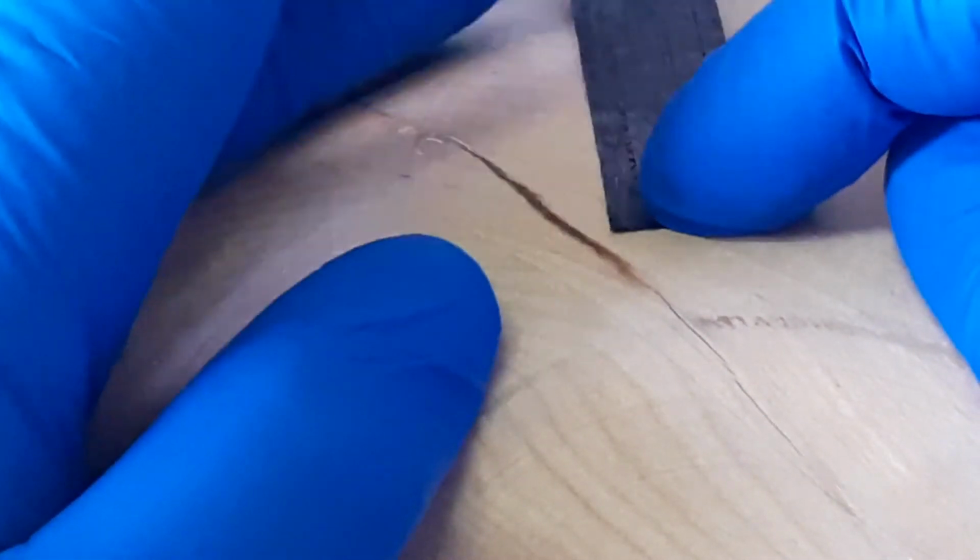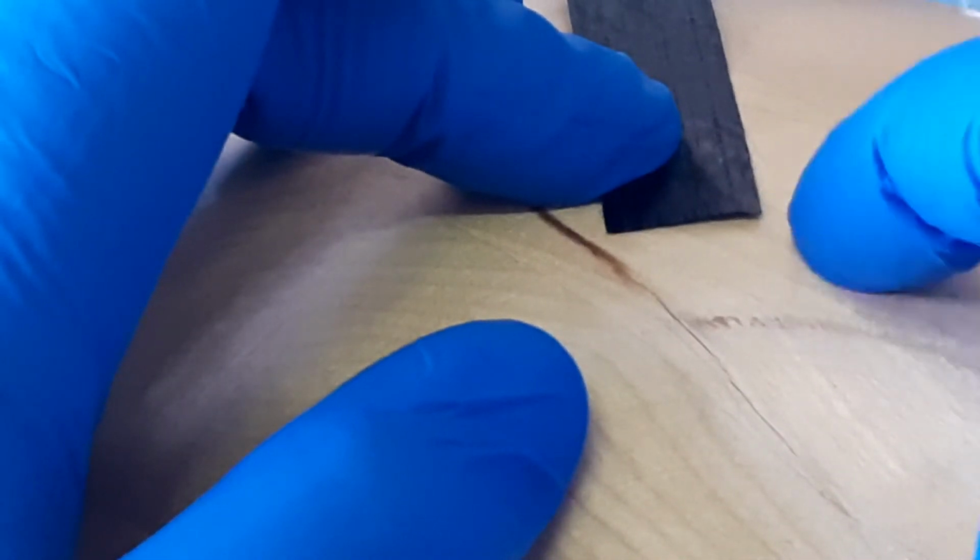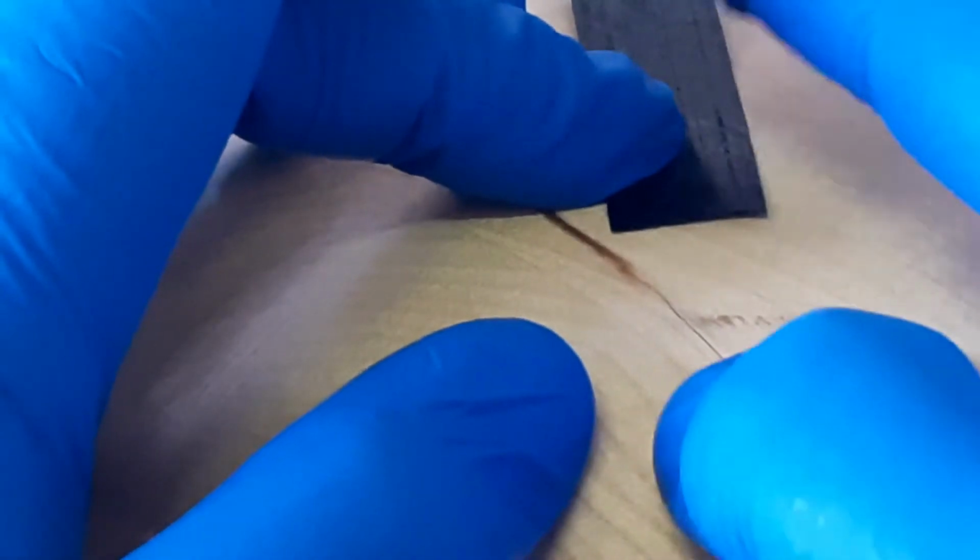Now actually, because I'm holding it at this end, this end is flat, but this end is lifting up because it cannot follow the curvature. Suppose you press it down on the center, and you leave it on this mold for vacuum bagging. Eventually you will have micro imperfections due to compression failure, due to compression over here, due to crimping of this fiber at this end.